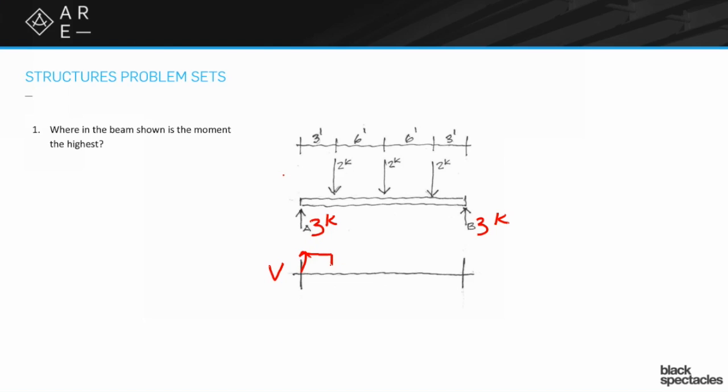So we're going to come down 2 kips, and then we're going to go across again till we hit that next load, and we're going to come down 2 kips, which takes us across the 0 line and puts us at -1. And then we are going to go straight across, and then down 2 kips, straight across, and then close it up with that last 3 kips.